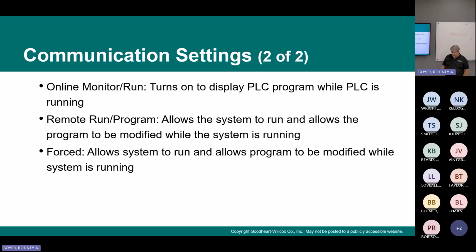And then forced: allow the system to run, allow the program to modify while the system is running. That's not what forced means anymore. You're intentionally driving an input or an output to a known state when you force. Remote program is what we use now for modifying the program while the system is in operation.